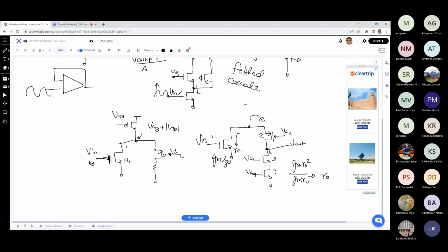And now if we just put the real transistor over here for the current source, here we can see definitely the voltages that you can apply over here, the absolute levels of the voltage that you can apply over here. Earlier, the lower level of the voltages, of course, here, if I talk about the lower level, you can go down, right? You can have lower applied voltages over here. If you apply the lower voltage at the gate, what will happen? The current in this branch will reduce, and more current in this branch will flow.